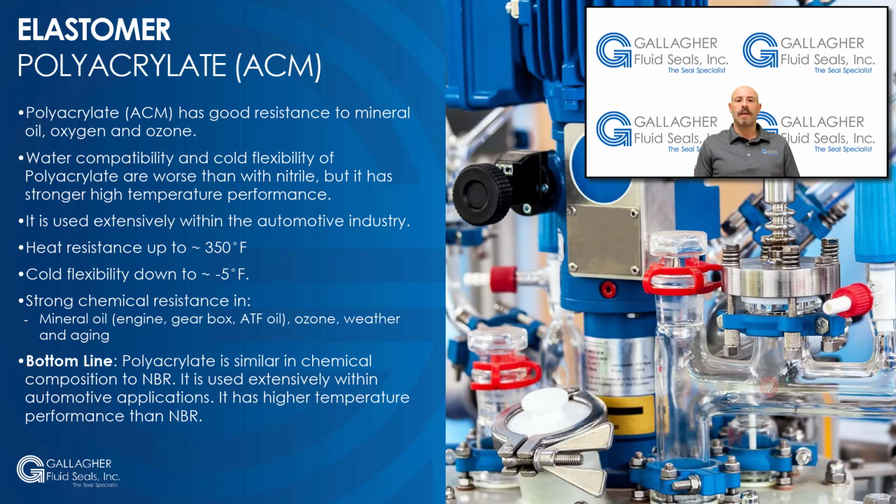Polyacrylate has strong chemical resistance to the following: mineral oil, such as engine, gearbox, and ATF oil, ozone, weather, and aging. Polyacrylate is not compatible with the following: glycol-based brake fluid, such as DOT3 and 4, aromatic and chlorinated hydrocarbons, hot water, steam, acids, alkalis, and amines.